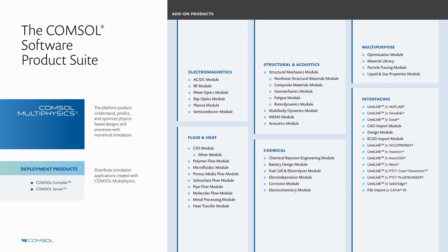So you have a parametric geometry inside any of the CAD programs and import it to COMSOL. It stays in a parametric manner. You can do some calculations, maybe modify the geometry, modify your design, and then you can load the model back to the CAD software automatically. So these are the LiveLinks. The "live" stands for this bidirectional link, actually.